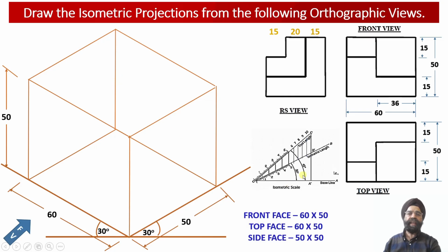This way, in this isometric projection construction, we have been able to obtain a cuboid block in which the front face, the side face, and the top face corresponding to the solid have been obtained in a single isometric projection construction.